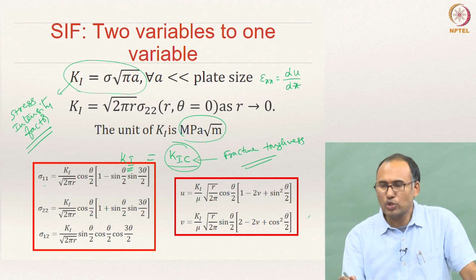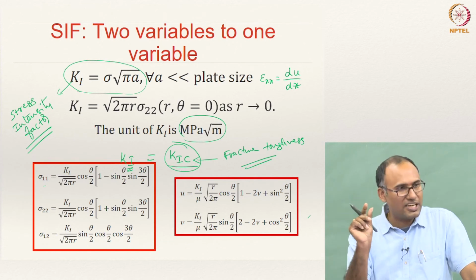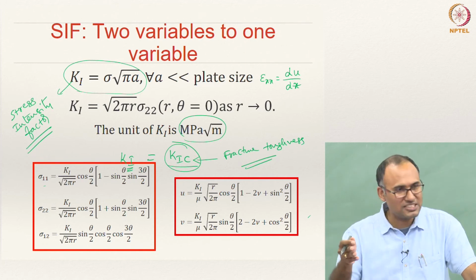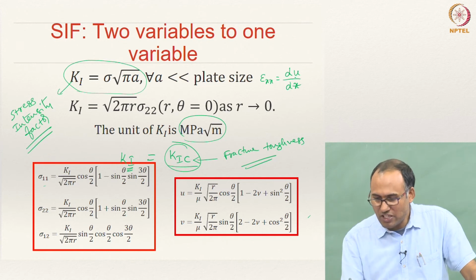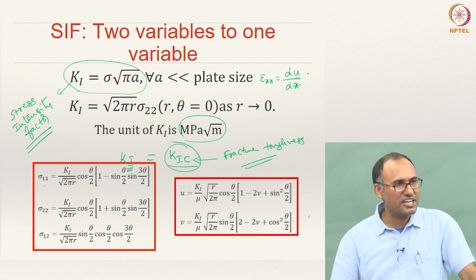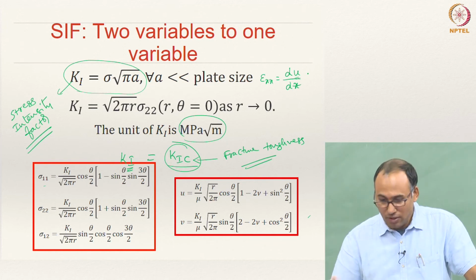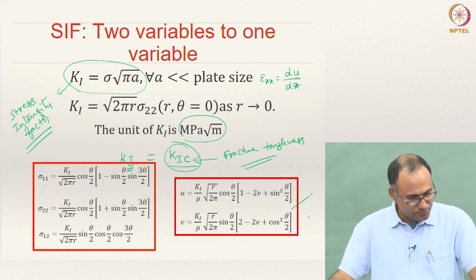That is the differential element if you take, and that is the proper way to define strain. Then how will you get displacement? You integrate strain, you will get the displacements and apply boundary conditions, right? And you do that, then you get the displacements, all right?